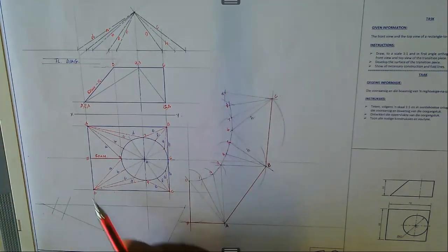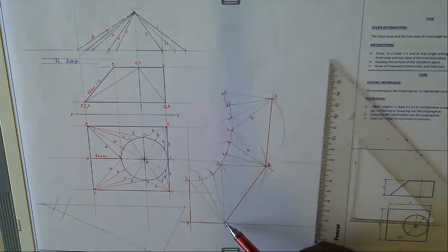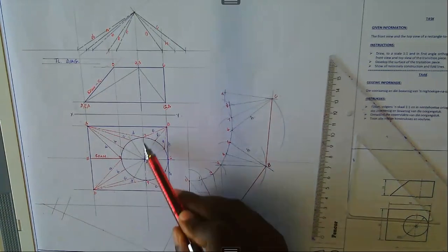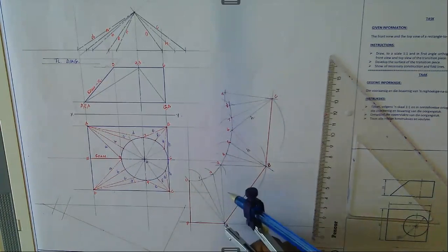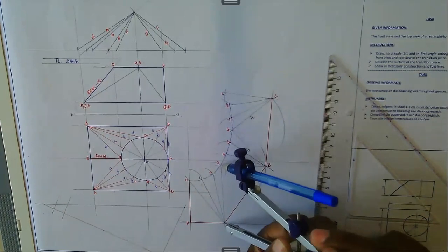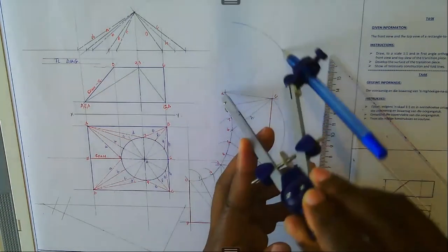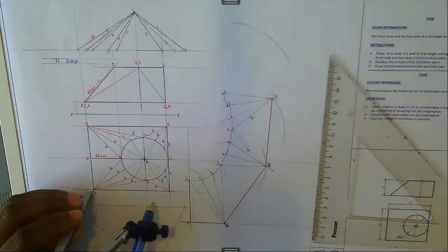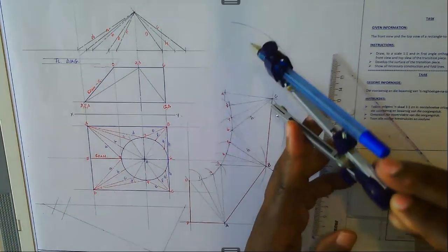So it's 9D, C, D, okay? This is the longer side, right? So we now need this one, right? Which is point 3 to A, is this, which is the same as 9 to D as well, okay? But I'm going to take this distance, right, standing at point number 9, describe an arc like that. Then take the longer side, which is C to D, which is this one, stand here and describe an arc like that.